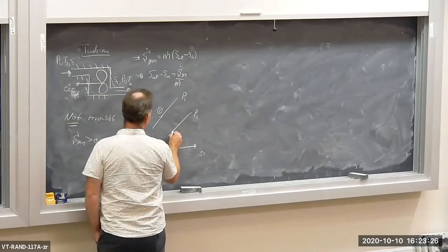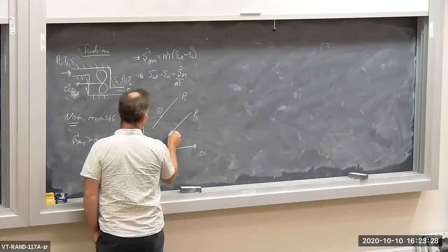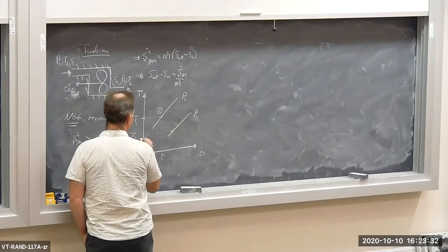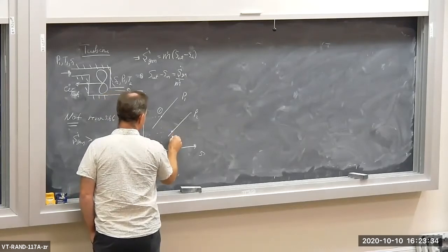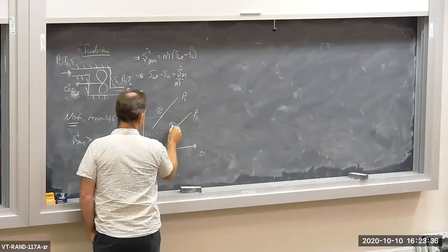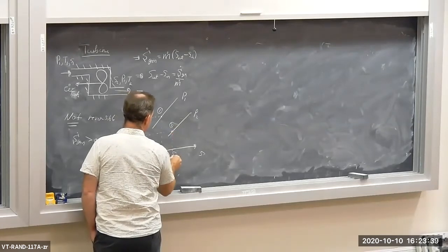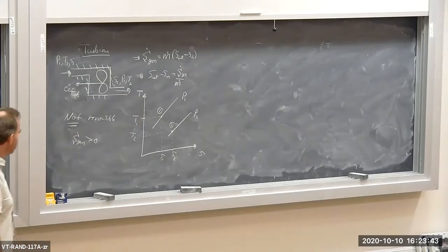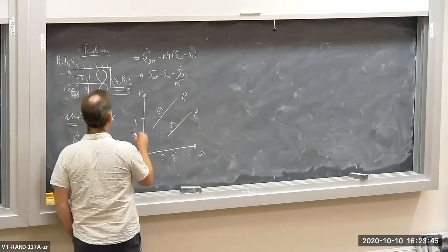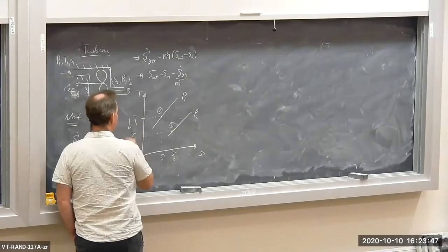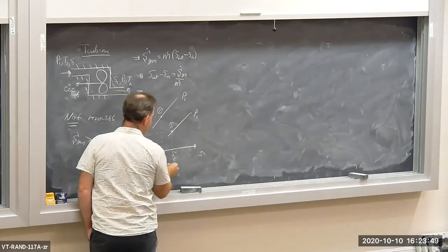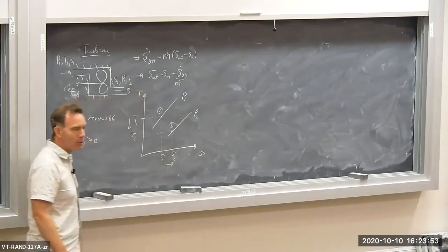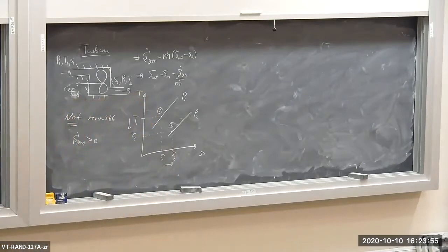And then I decompress down to a pressure P2 and a temperature T2. So this is state 2 right here. And this is S2. So temperature falls. I extract some of the energy in the form of work. There's some irreversibilities inside. So entropy, specific entropy, also goes up.